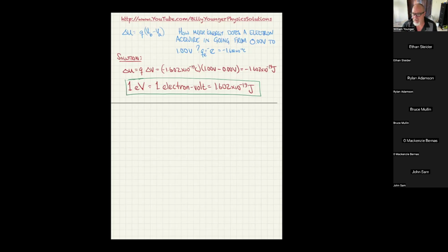So over one cycle, they calculate the average of the square of the voltage, and then they take the square root of that, and that's where they get the 120/125. If, for instance, we called it 125 and I multiplied that by the square root of 2, I would get about 177. So that's really what the peak voltage is.